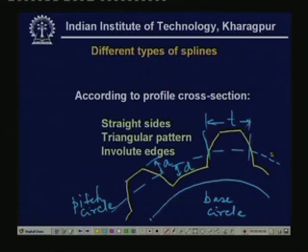and if you draw a tangent to this base circle, then we get an angle. This is the pressure angle, which is very important for force transmission, and this angle should be chosen such that the maximum torque can be transmitted.